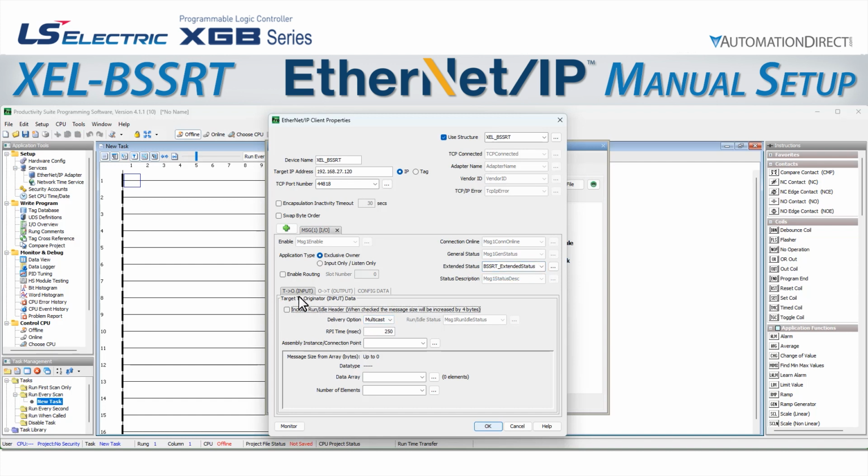For the message itself, we see there are 3 tabs. Since this is an I/O message, there is input data, output data, and config data. On the input tab, we need to decide if we need to include a run/idle header. We also need to select unicast or multicast, RPI time, assembly instance, and a data array to handle the information transfer. For this example, the Productivity will be the only scanner reading information from this bus coupler, so we will use unicast. Multicast would be used if we had several scanners using listen-only connections to the bus coupler in addition to our exclusive owner connection from the P1 550.